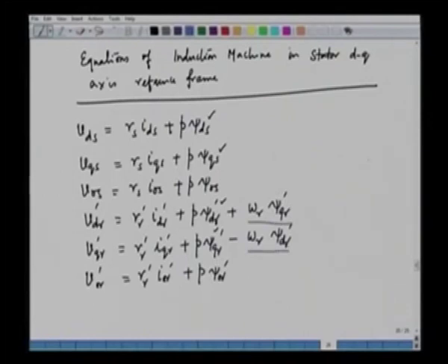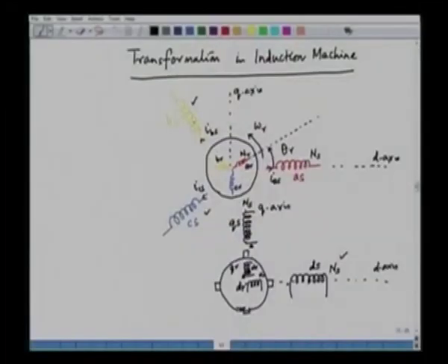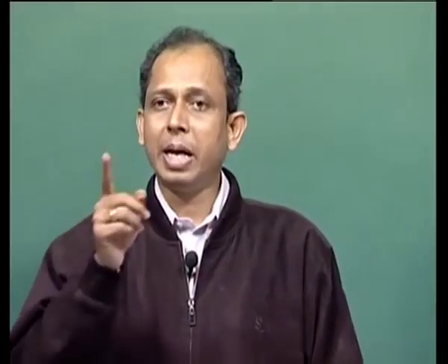All right, and the rotor is rotating in which direction? If we see, the direction of the rotation is from A to B to C, phase A, phase B of the stator, phase C of the stator. We are assuming that the revolving field is rotating from A to B to C. So, the revolving field is in anticlockwise direction, and the rotor is trying to catch up with the rotating field, and that is rotating in the anticlockwise direction.